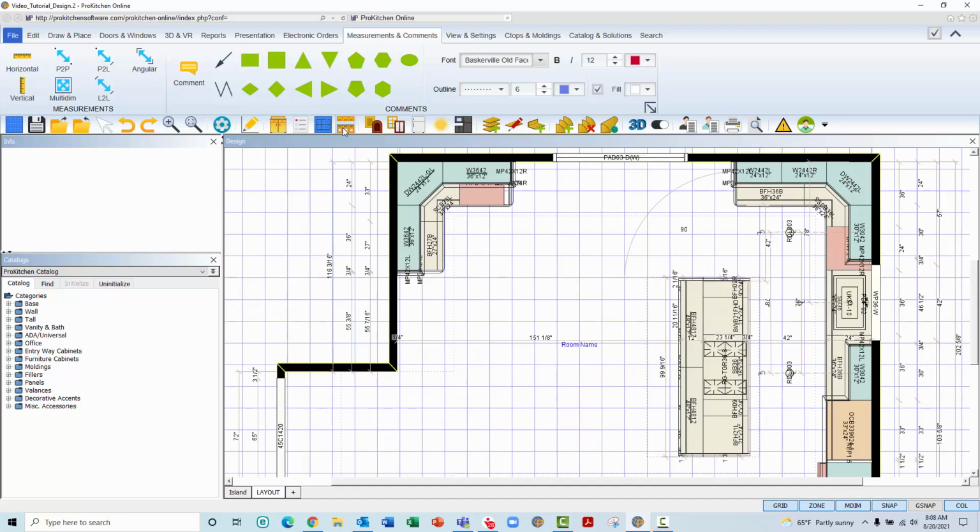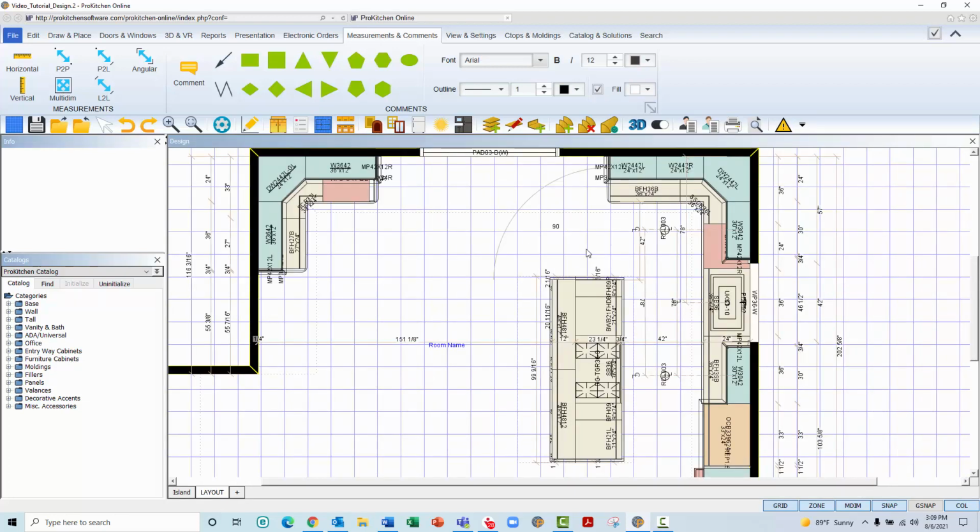The Comments tool is an incredibly useful tool to communicate extra or more detailed information to the installers, or provide comments or directions to supervisors, other designers, or assistants. To place comments in the design, navigate to the ribbon. Left-click the Comments icon. Bring the mouse into the design and left-click on the grid.